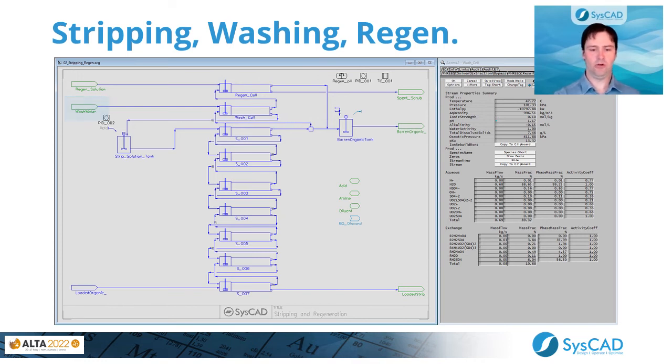As I mentioned before, this creates conditions that are very similar to extraction, because you add wash water with the organic, which contains lots of acids. You end up with a dilute acid in the aqueous. And so any entrained uranium in the organic, such as any entrained aqueous, will, when it hits the wash cell with wash water, be re-extracted onto the organic, which will then go to the regeneration cell.